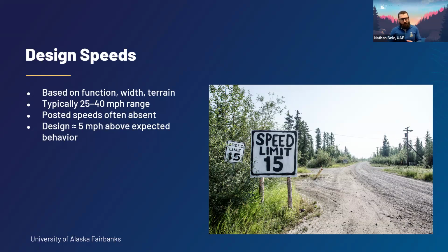So the core streets, primary residential, being 20 to 25 miles an hour posted, and then the non-core going up to 35 posted, or a 40 mile an hour design speed. Again, as Billy mentioned, those going out to either the airport, landfill, material source, or other community or cultural sites that are outside of the village, like say a cemetery.